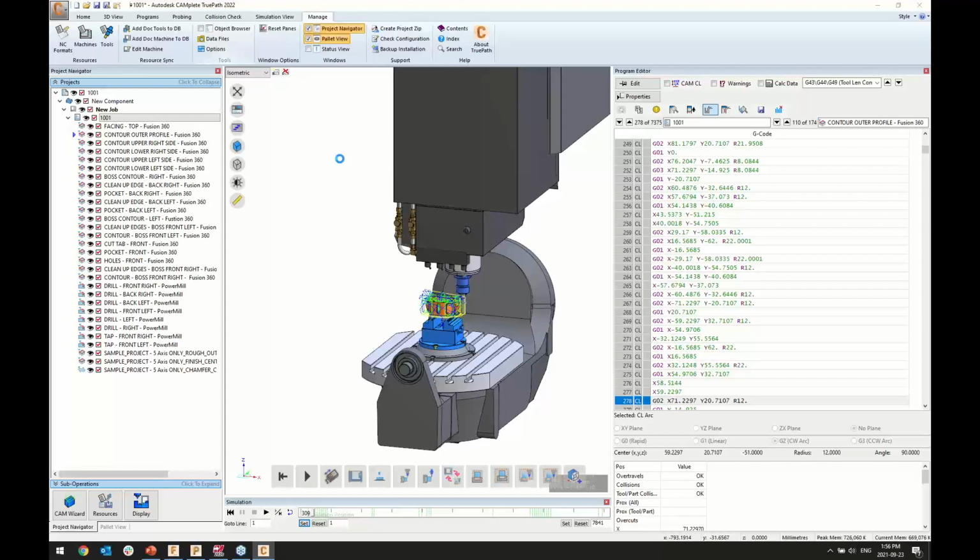So again, that's going to be a little bit of a combination of how the project as a whole is set up and how the post-processor in itself handles those movements. So in some of those retract movements, by default, it will retract to the home position of the spindle, but we can define what is called safety volumes around particular elements.